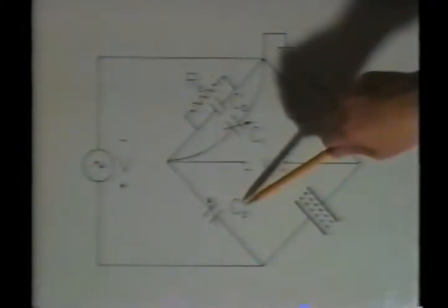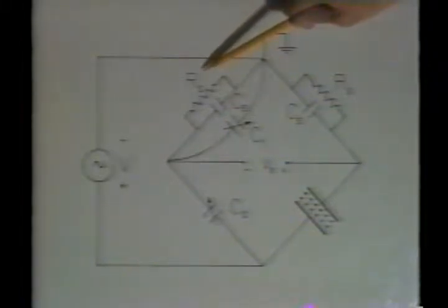With the introduction of the array, there's a change in current through the parallel plate capacitor. This results in a change in current in the resistance in the right leg, and hence a change of voltage across the resistance. Because the current through the left leg has remained essentially the same, this change in voltage is the measured output voltage.